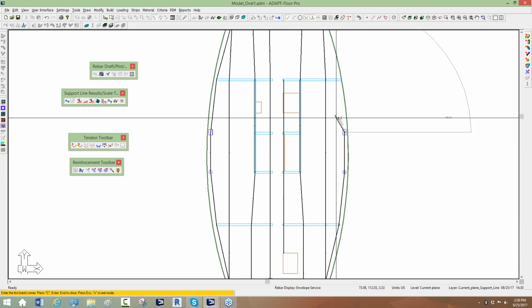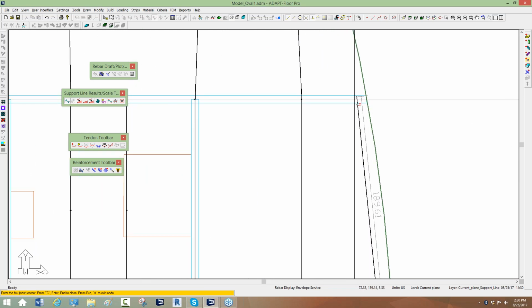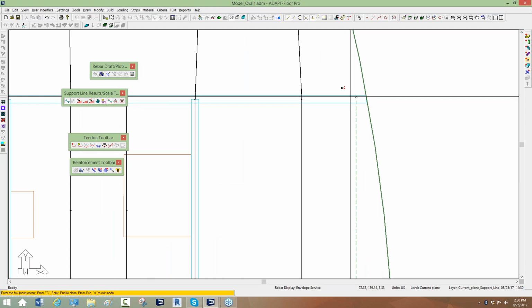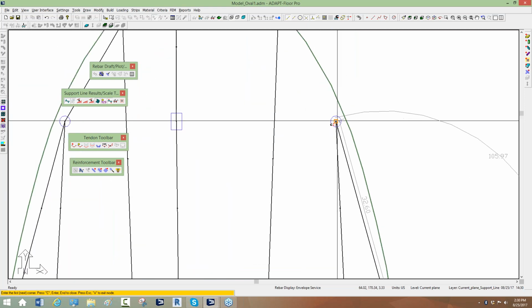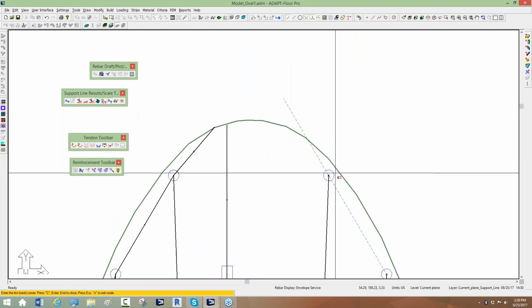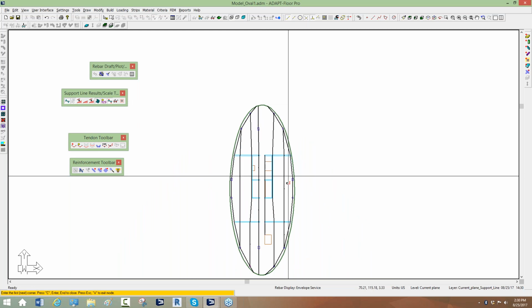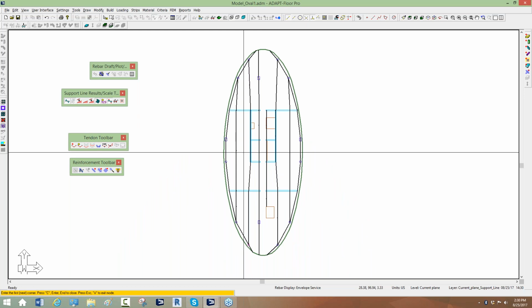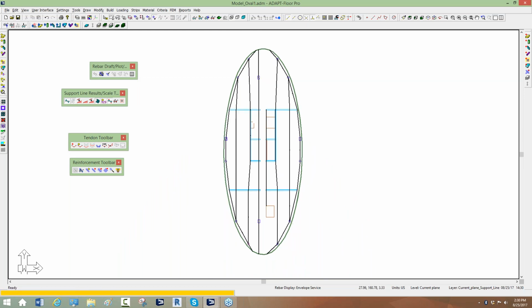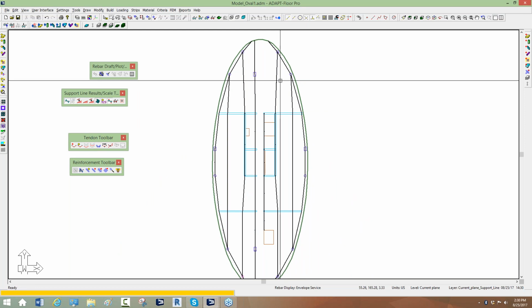And because I'm mapping my uniform cables to these strips, then I have to follow essentially the shape of what I want my uniform cables to look like. Now that may be slightly different than how they're actually represented on plan. So again, there's more ways than one to do uniform cables. We're just showing you a map, a banded arrangement of the cables here. So we have several conditions here where we need splitters.